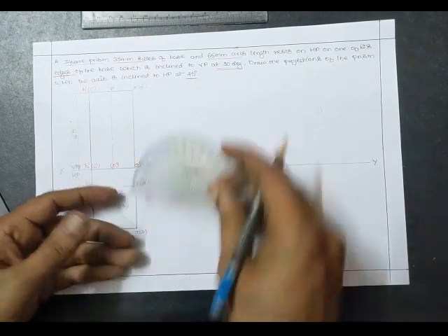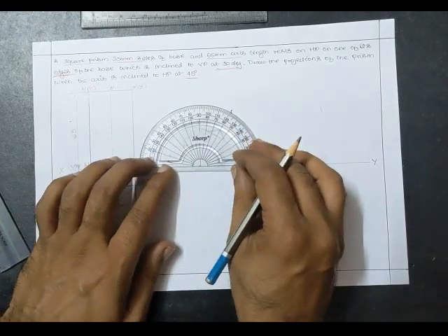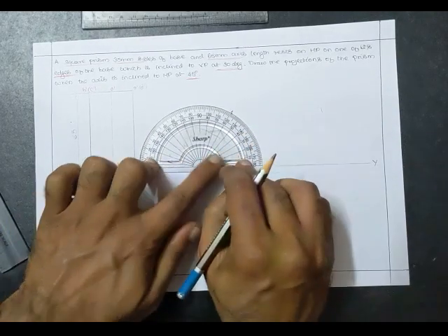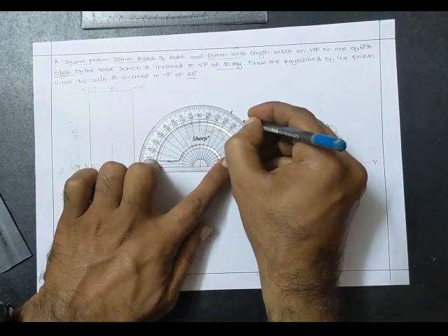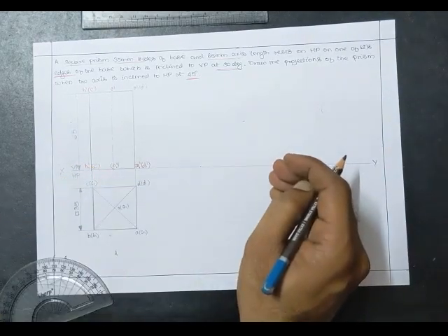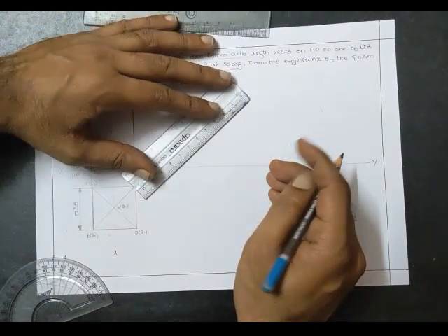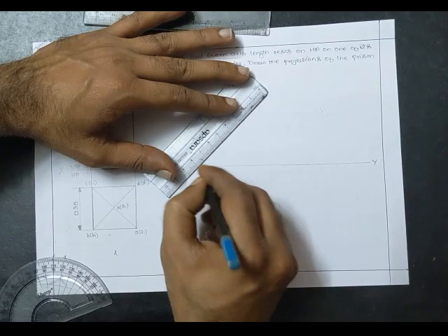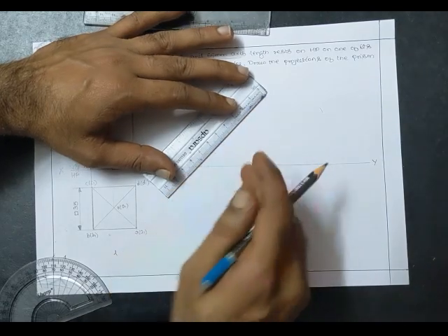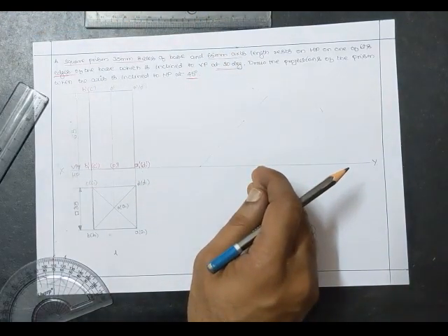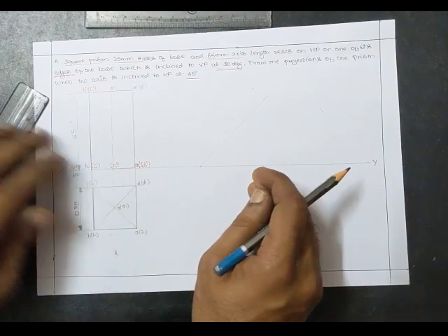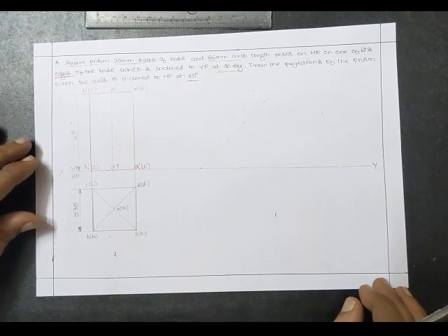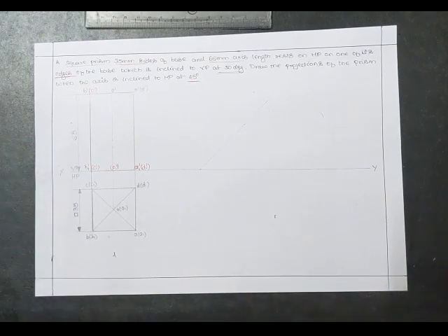This is sufficient, I guess, right? Next, measure an angle of 45 degrees. Once you measure that, extend the line. Be careful, the line which you construct is very thin. Once you construct it, you need to transfer the first position to the third position.